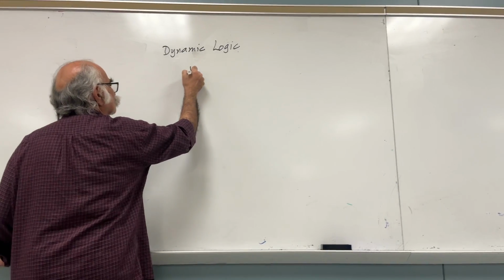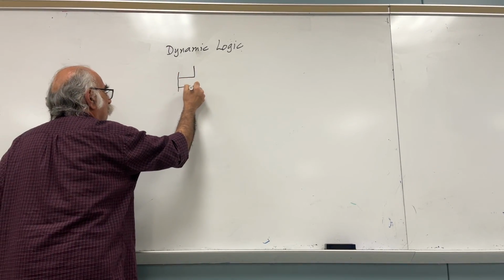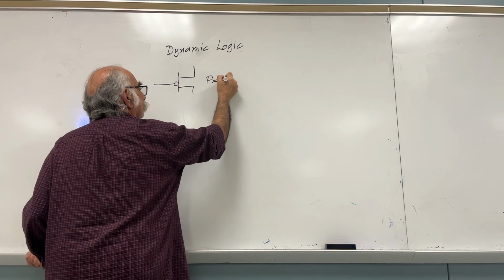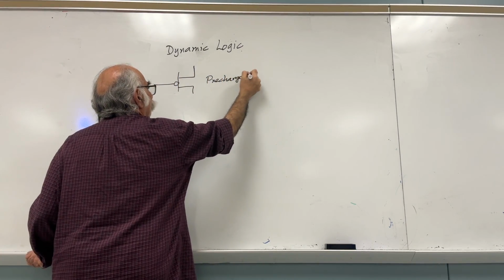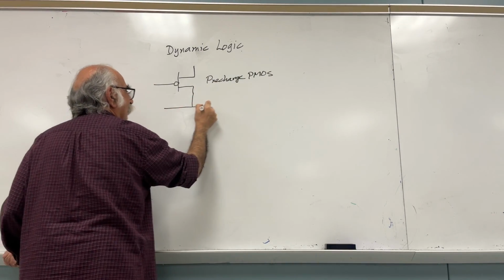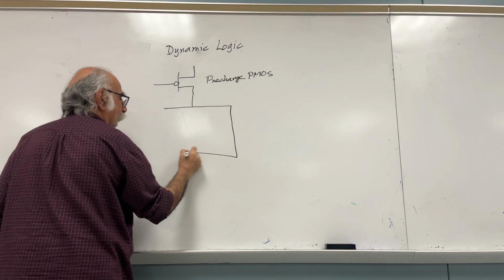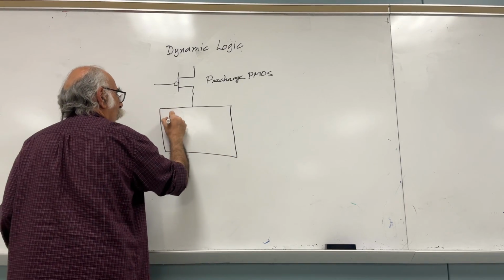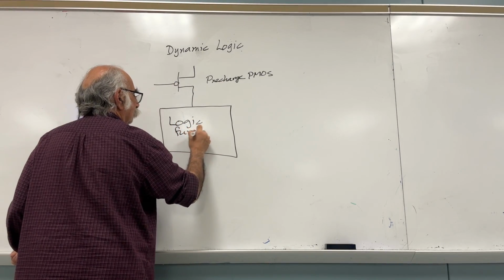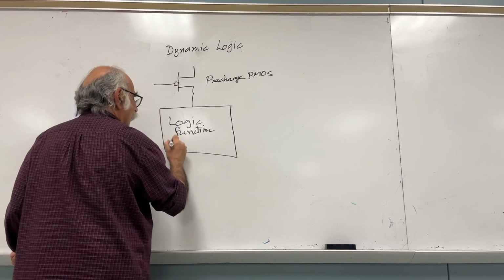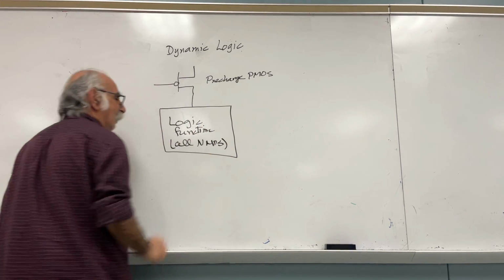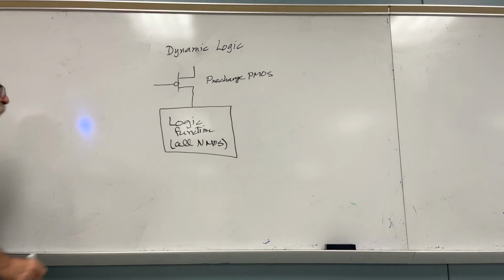So in dynamic logic, we have only one PMOS, which is called the pre-charge PMOS. And then we have the logic function, and this is all NMOS.